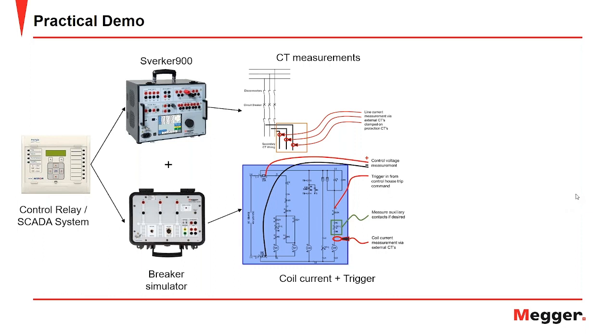Another question came in as well. How can I check CB motion and conventional test? I've never done this test before. For the CB motion, we utilize a transducer. Basically, it's a device that converts the motion measurement, whether linear or angular, to an electrical signal. I connect it to my test equipment, a circuit breaker analyzer, and measure that motion.